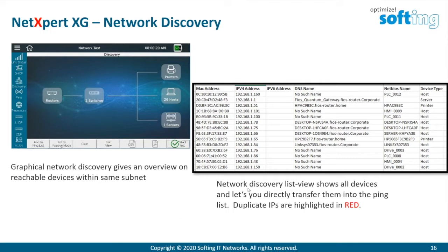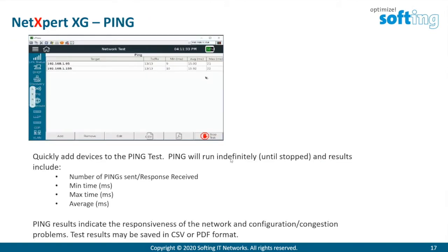I did have one particular customer in Ohio, a plastic container producer. I went in and did a demo for them, and they allowed me to connect up to their industrial switch. We ran a test like this, and boom, 3 duplicate addresses came up. And I was like, I think you guys might have a problem. And the maintenance guys there were like, we told IT we've had an issue and they just don't support us well. Well, they bought it on the spot because this gave them the evidence to talk to their IT group and say, hey, we're seeing this, what's going on? So anyway, that's another real life story.